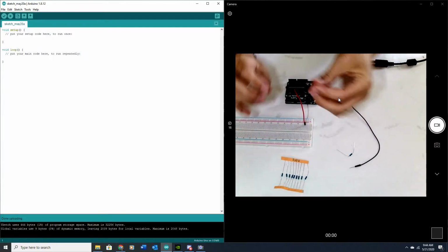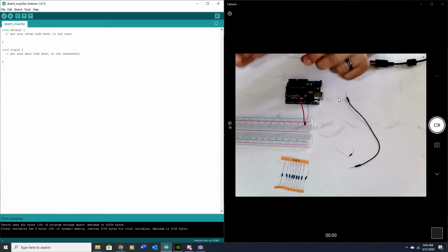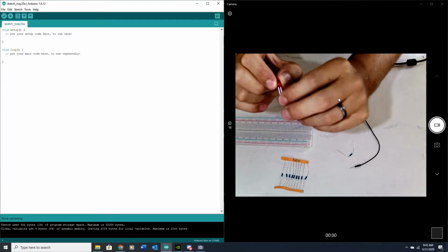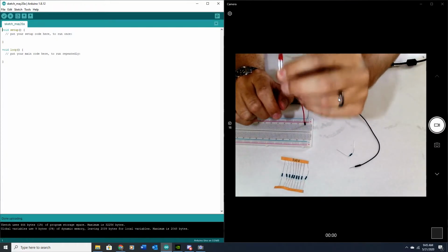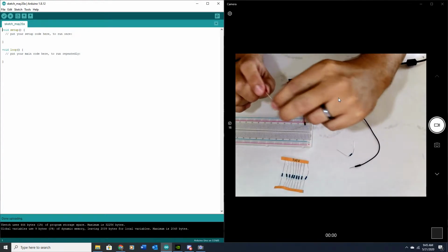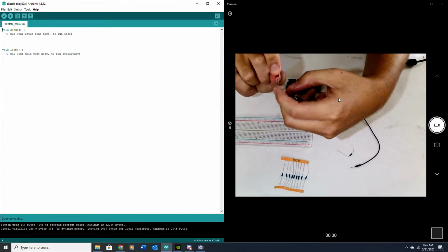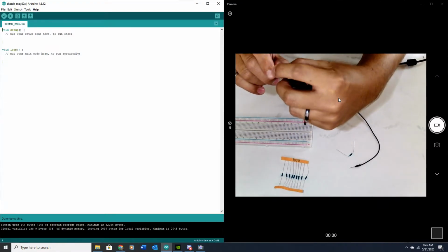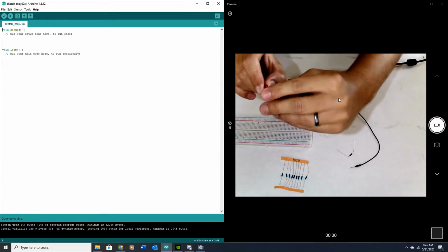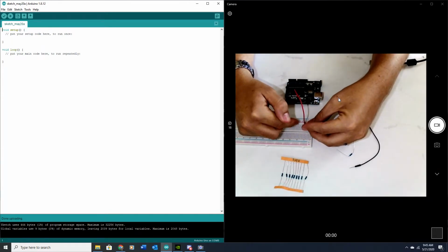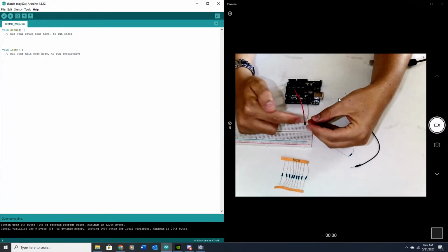Now your LEDs have two wires, right? They have an anode and a cathode, basically a positive and a negative side. And the reason they have this, because it's an LED, it is a light emitting diode. So the diodes only allow current to pass through in one direction. So basically the positive side, if you're going to power it, always has to be the longer side. That's the anode. So if I want to plug this in, I want to make sure that the positive voltage is going to go into that longer terminal.